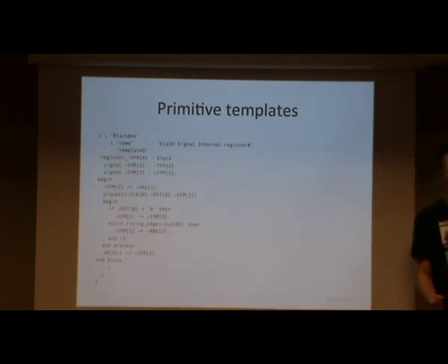So for example, if you have different FPGA vendors, you can put in your own template for the same function. It's sort of like a module system, but for primitives. Some of the synthesis tools from one vendor can work better with one kind of HDL than with the other, so you might want to change that, depending on what you're compiling for.